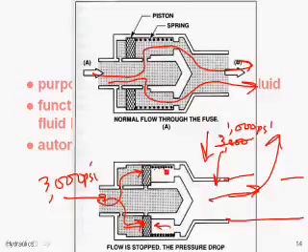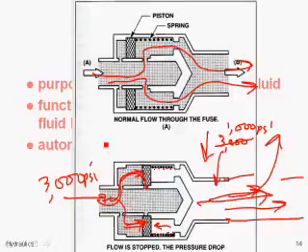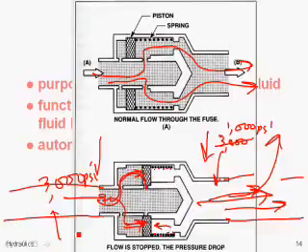It's actually going to overcome this spring pressure, and it's going to push this plate over, and now the fluid can't go anymore. So downstream, you won't have a leak anymore, but also, unfortunately, downstream, nothing there will work. However, everything upstream on the pressure line is still going to operate.